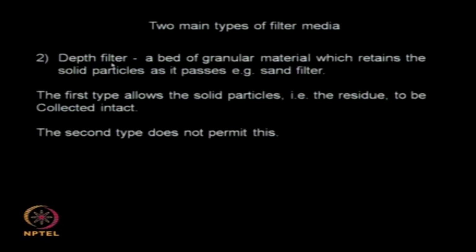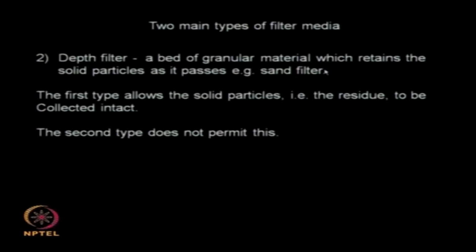The other approach is the depth filter. So you have a bed, granular material bed of varying particle sizes, granules, pebbles, sands, which try to capture the solids present in a fluid. Especially this type of depth filter is used in water treatment facility. They are also called sand filters.